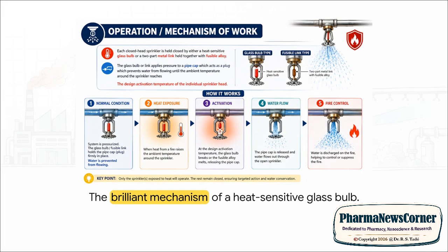Take a close look at the glass bulb holding that pipe cap in place. That little bulb is actually filled with a heat-sensitive liquid. As the heat rises, the liquid inside expands. Once it hits its exact, precise design activation temperature, the glass shatters. That drops the pipe cap plug, and bam! The pressurized water bursts out through the deflector. It's a completely mechanical and incredibly reliable failsafe.